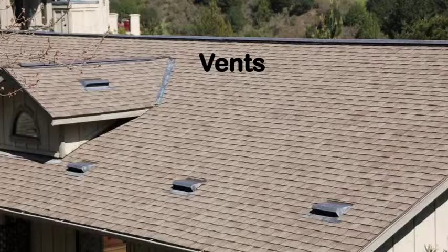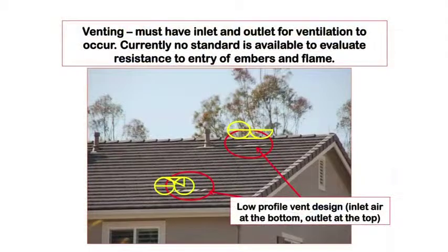So enclosed spaces that are typically unconditioned are typically vented. So if you're built on a crawl space, you're going to have crawl space vents. If you're built, and you have an attic, you're going to have a vented space there. If you're a cathedral ceiling, you could have venting depending. So here's the idea that you have inlet and outlet in each space. So if you have a foundation or crawl space, you're going to have air coming in, air going out. Theoretically, the dry air comes in and more moist air goes out.